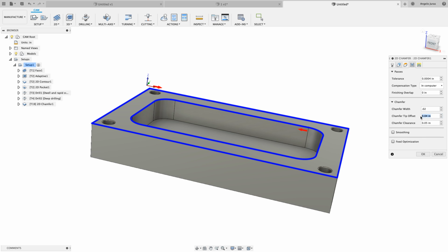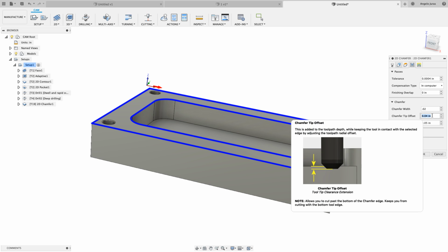And this comes into play if you have different geometry pockets with steps where you want to make sure the tip of the tool doesn't hit the bottom of the pocket or floor of the part. We've got this pocket here is 1/2 inch deep, so we're not concerned about that. There are some things you can do to drive the shank or the shaft of the tool away from the wall of the part. That we'll cover in some more live streams where there's more detailed of a part, but that's what you enter here. Let's do 50 thousandths, and I have too many decimal points.